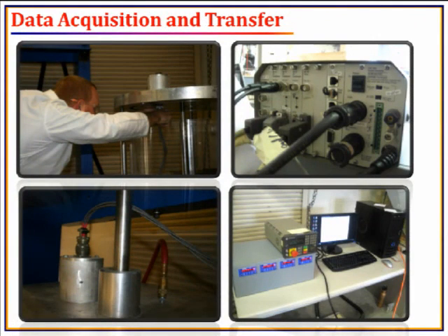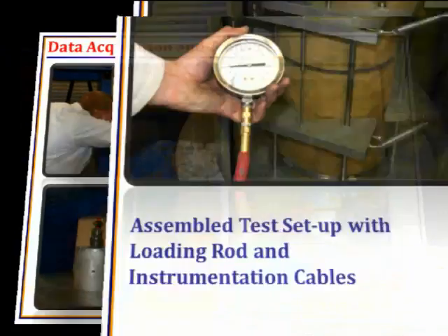And this is the instrumentation phase. From the load cell, it connects up to the top of the acrylic chamber, and from that acrylic chamber, it is connected to the MTS controller as well as the transducer indicator, and those 2 stations are also connected to the computer. We collect the voltages and then we convert the voltages into our raw data.